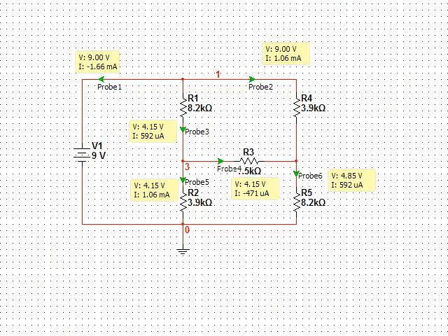we have made the simulation of the circuit. This is the simulation values. Now the simulation program Multisim is working. As you see, it shows the same values. The voltage of this point is 9. The current through the voltage source is minus 1.66 milliamps. The voltage of node E1 is 4.15 volts. Voltage of E2 is 4.85 volts. And we can easily calculate the other values of the circuit.